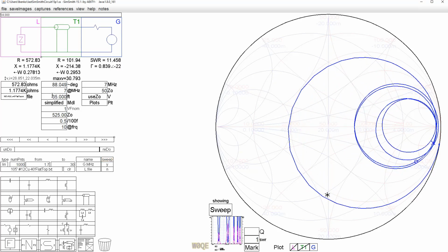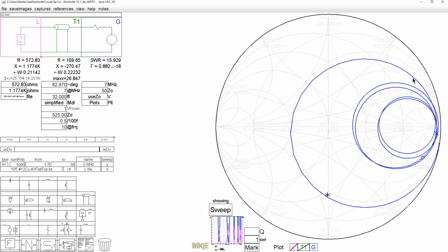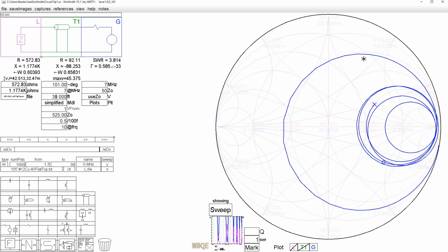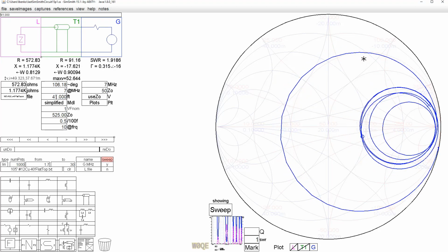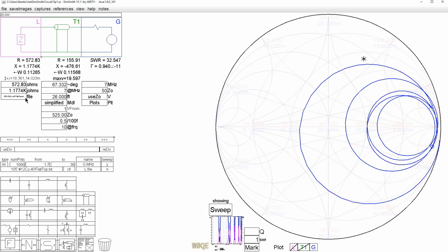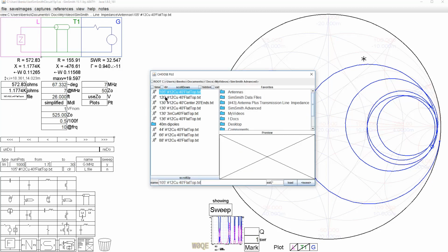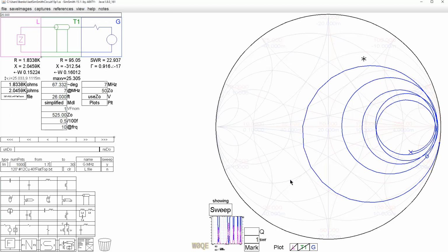So if we look at something like this and say, where's the frequency over here that we can go down to? We're at 3.8 megahertz. We could stretch that probably to 3.5, be okay. So a 105-foot dipole, we can make work on 80 meters. And this is for lengths, most normal lengths would be fine. So you might want to go up a little bit higher. I don't know. Let's say we made it a 120-foot dipole.